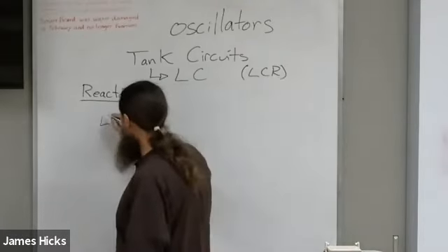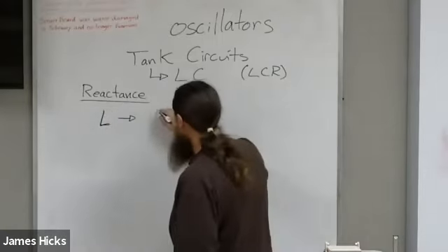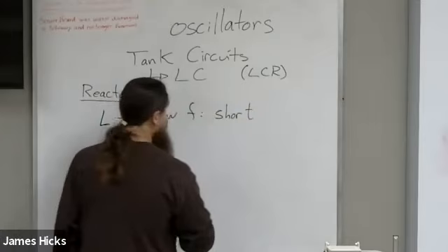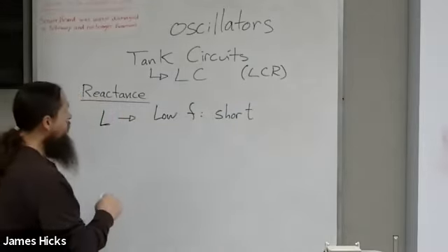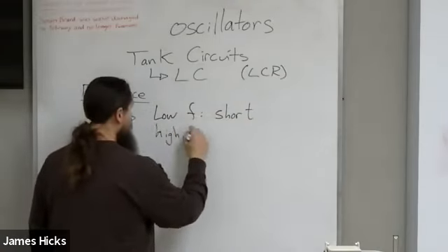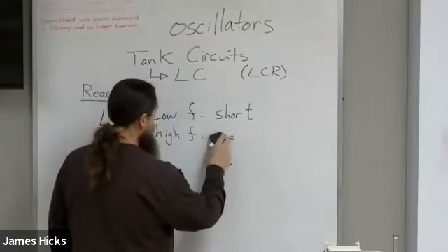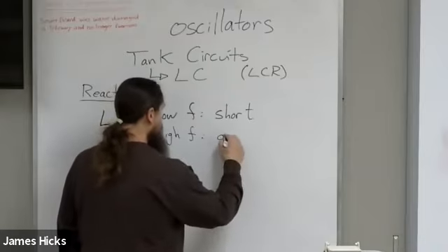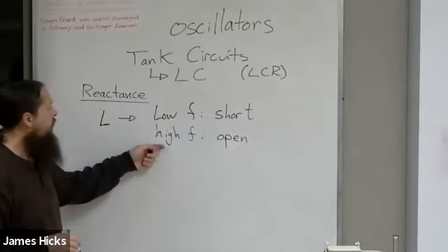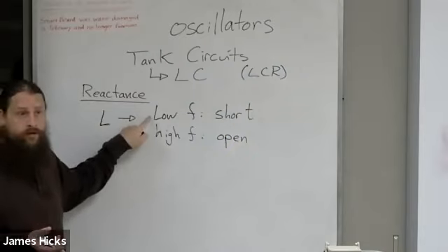For an inductor, low frequencies, it looks like a short circuit. For high frequencies, it acts like an open. So low frequencies, an inductor has a low resistance. It's just a piece of wire.